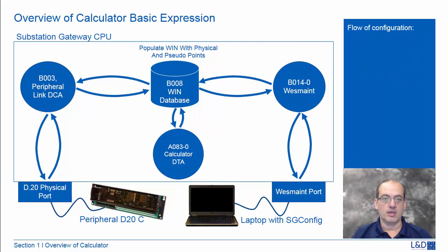Okay, so for our basic example, let's say you've got two redundant points that are sensing the same source. For some reason, if one of these sensors fails, then those 2 points are going to be different, which we don't like. So we would like to set up a basic expression that whenever these 2 points are different, we raise an alarm.